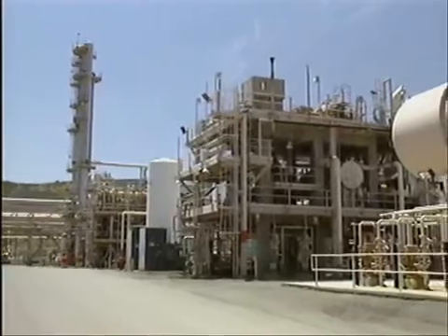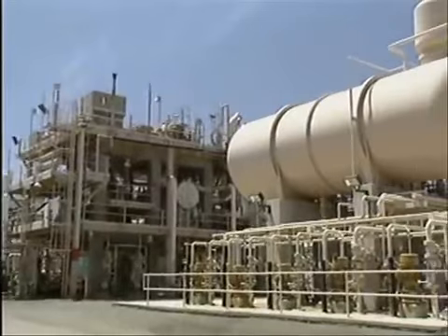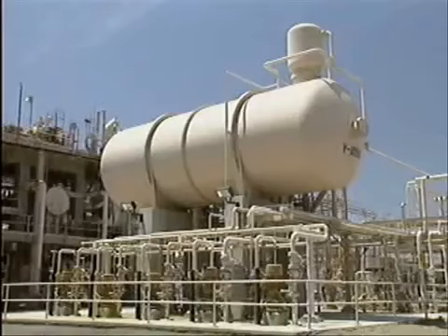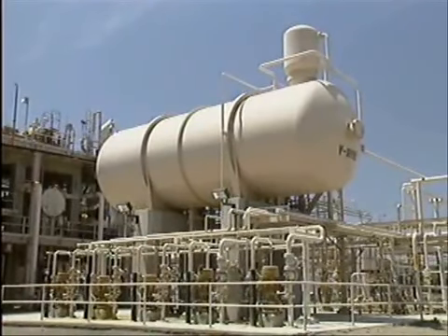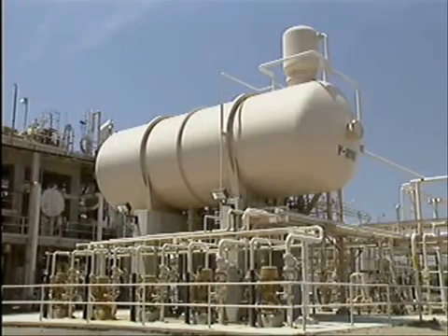You see, by law, safety valves can't be isolated from the systems that they protect because of the damage that could occur if the systems were operated without protection. So, whenever a safety valve is damaged, its system must be shut down while repairs are made.